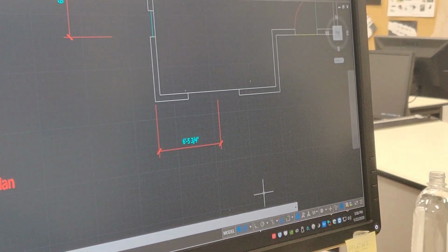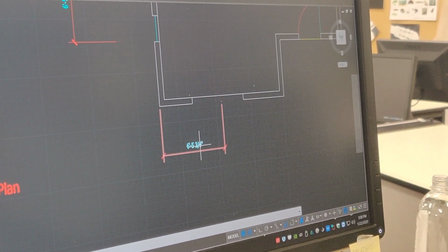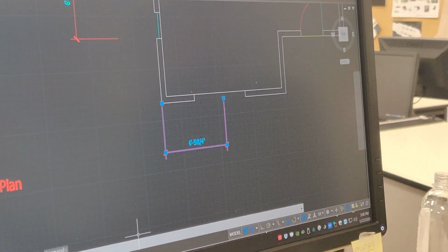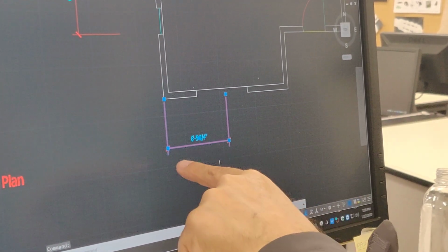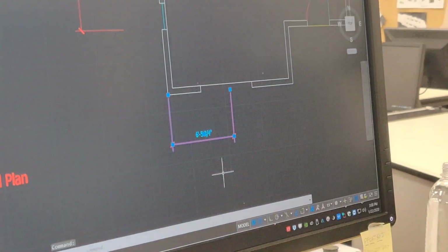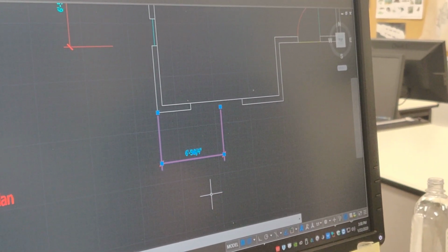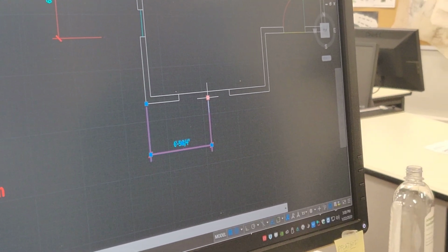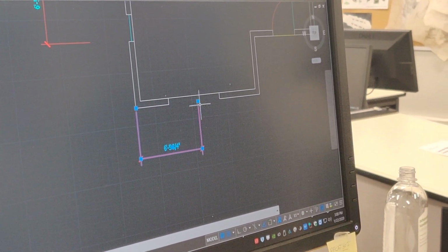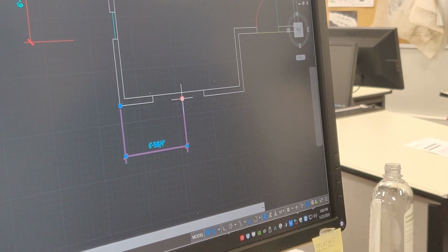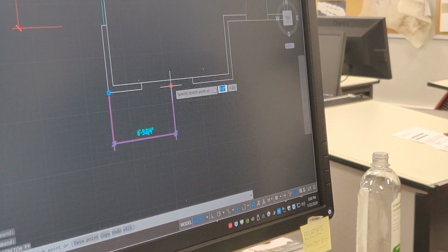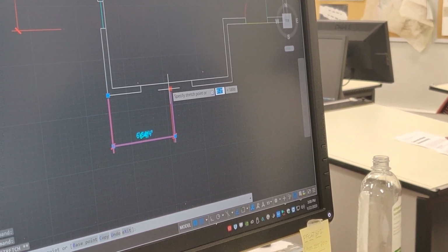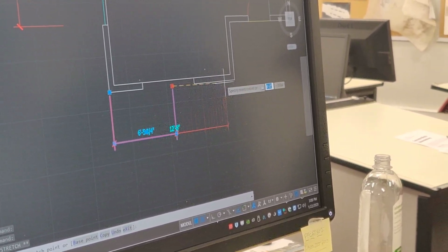No. Okay? So what I'm going to do is I'm going to select that right there. And now, if you take a look, it has those little boxes on there. Those are called grips. And so that's where you can kind of grab it and move it. So all I'm going to do is come down where this grip is on that node there, and when you get it right over, it'll have that red box on it now. See that? Click, left click, and now look what happens.